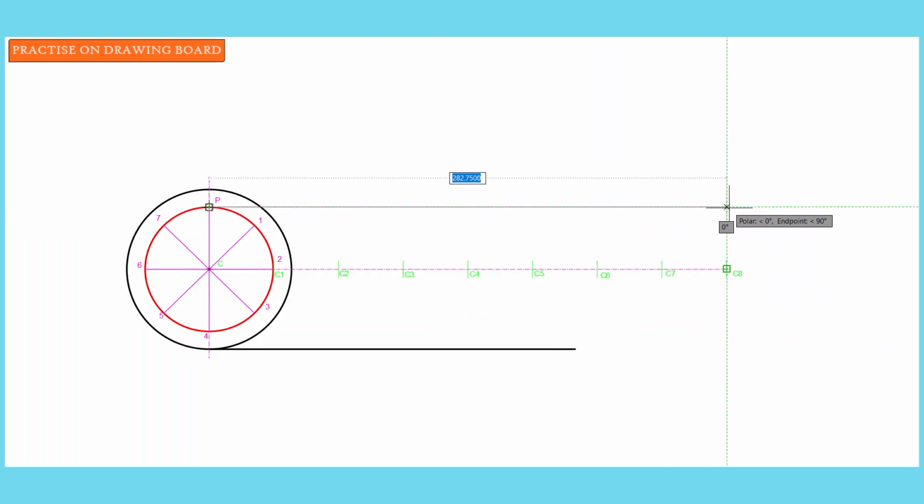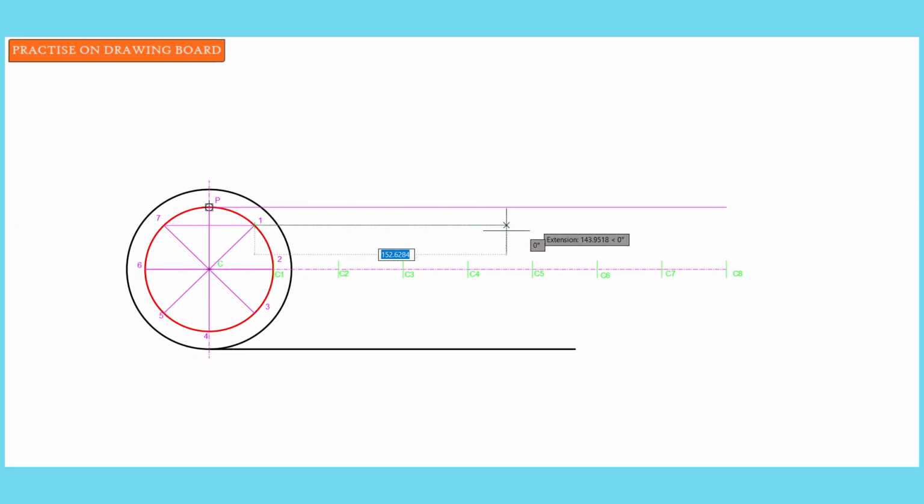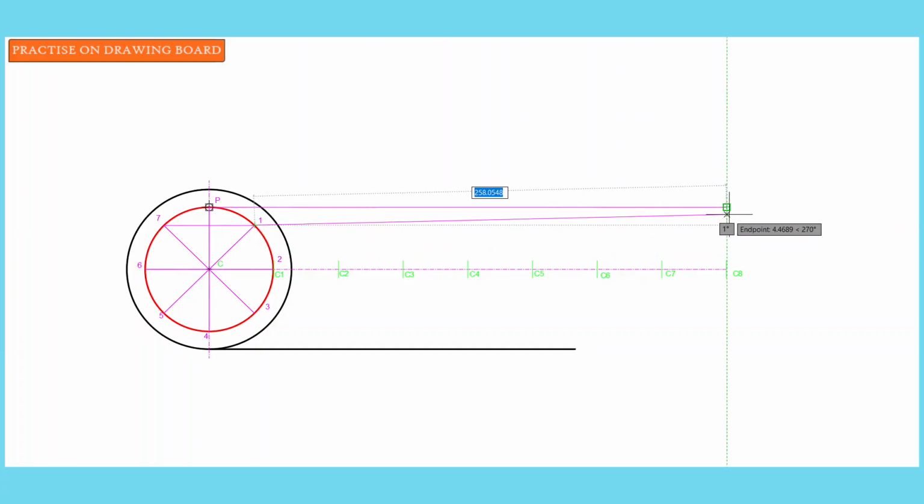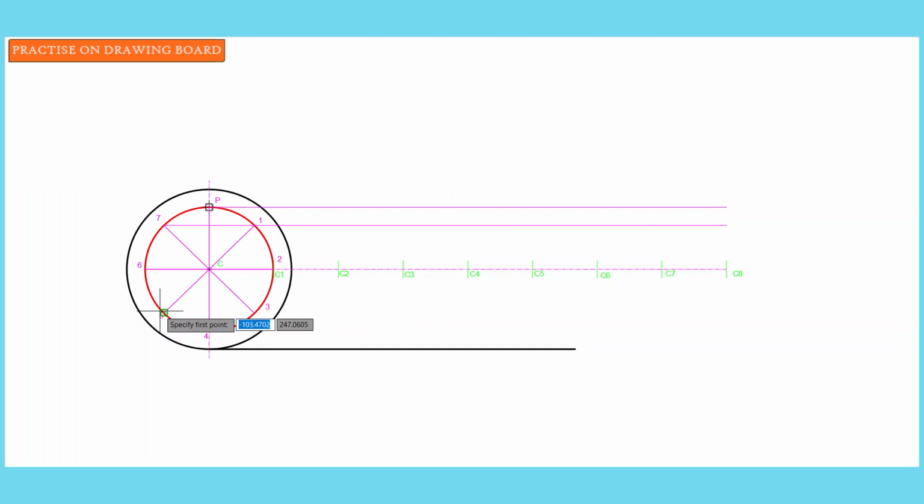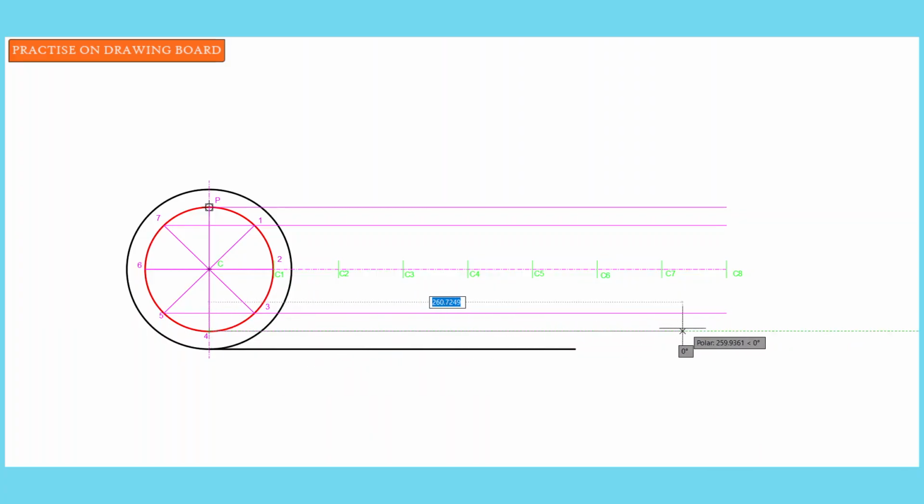Now we can draw in our horizontal lines. We draw a horizontal line with your T-square and pencil from the point P, and then 7 through 1, 6 through 2, 5 through 3, and then 4. Okay, so we have our horizontal lines in place.